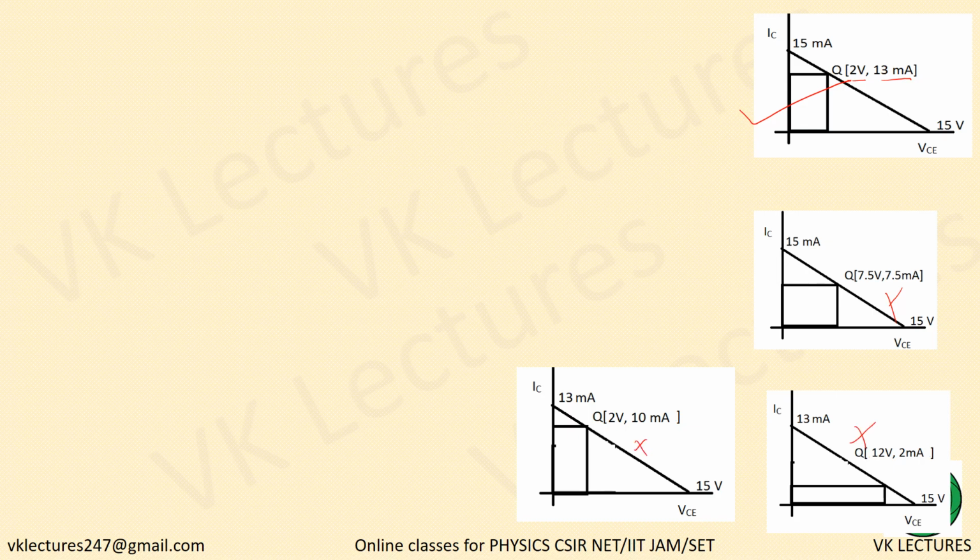Others no. Now if there are two options with the same value, what you have to check is for VCE. VCE is 15 volt and what is IC? That is when IB equal to 0, the maximum IC and the maximum VCE possible. This is the load line, maximum IC and maximum VCE possible.